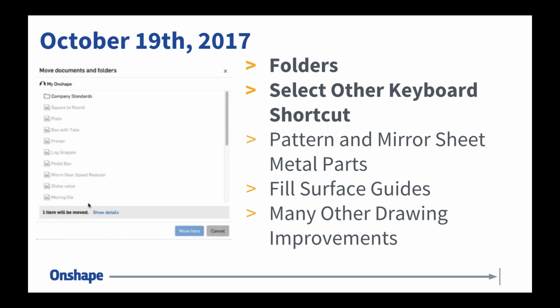But another important drawing improvement is copying annotations. So you can Alt-drag and copy a note, or Alt-drag and copy a balloon or a tolerance symbol, right? So Alt-drag copying annotations on your drawings is just a really easy workflow for adding in multiple annotations, multiple balloons, those kinds of things. So those are, at least in my opinion, the big drawing improvements.